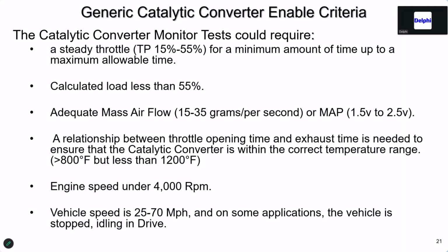And think about this, a number of cars have gone back to MAP sensors. Now, if you're on a Honda, that's not going to work because a Honda tops out at about 3 volts. So you want to be about 1.25 to 1.75 volts on a Honda to be in that window. Otherwise, you've got too much load. Once again, they infer temperature of the exhaust. Look at your global scan tool.